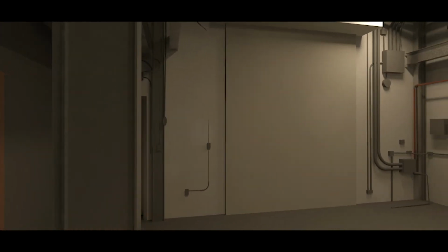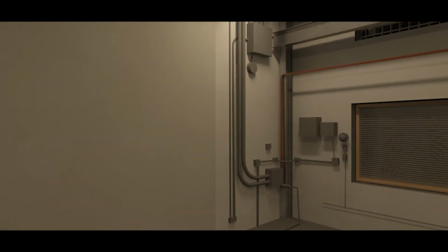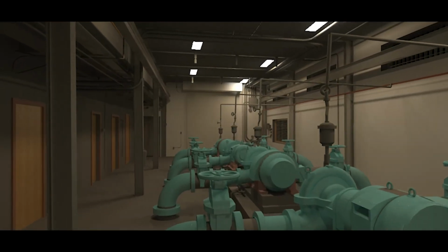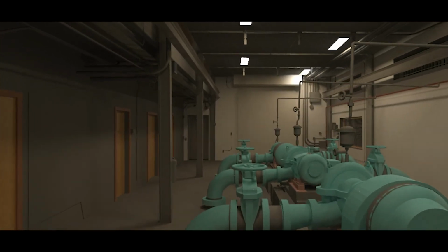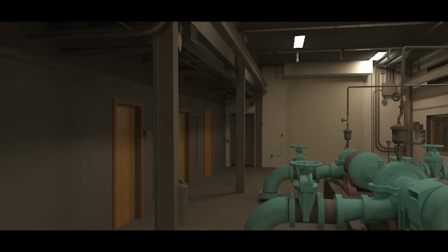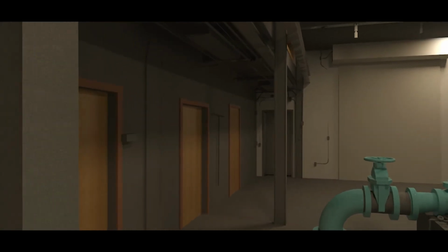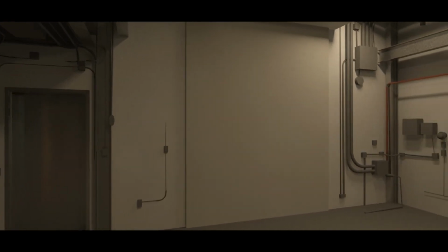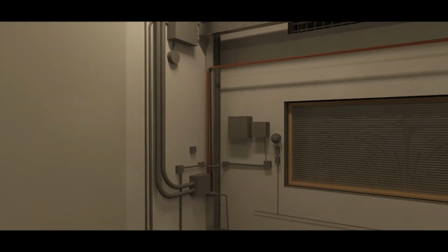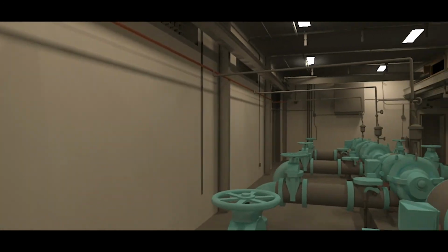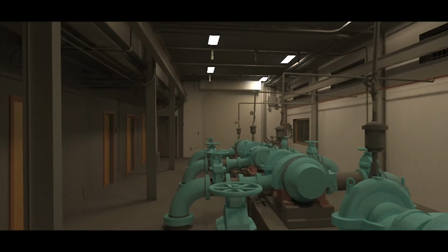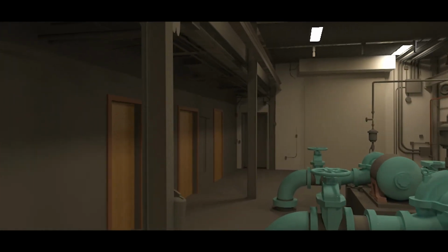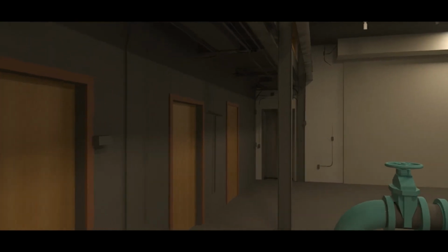Of course. So a family in Revit, because I don't think I actually defined that term, is sort of like an individual modeled object. For instance, if you look at the video that's playing to the right, that window that we just passed is a family. These individual pumps could be a family. The doors could be families, the lighting could be individual families. So a family is like an individual modeled object. A family can be created by anyone. You can create your own families in Revit. They can be parametric, meaning they update based on other factors within your model, or they can be placeholders that represent an object three-dimensionally, visually.